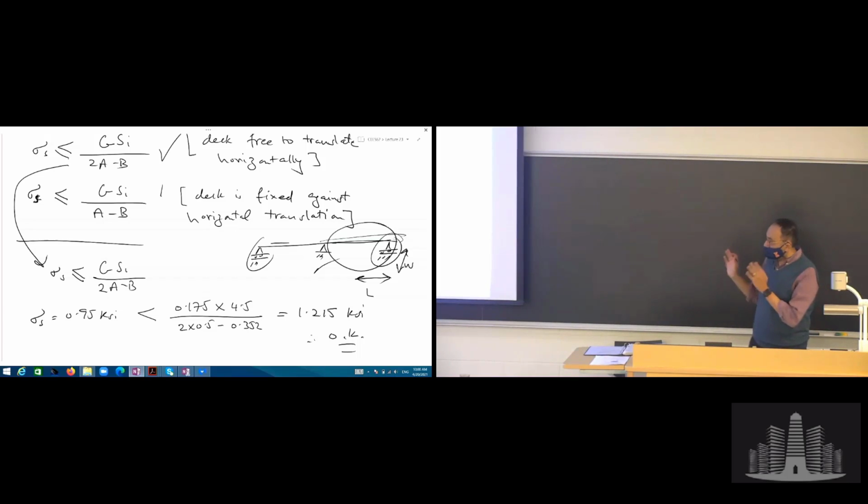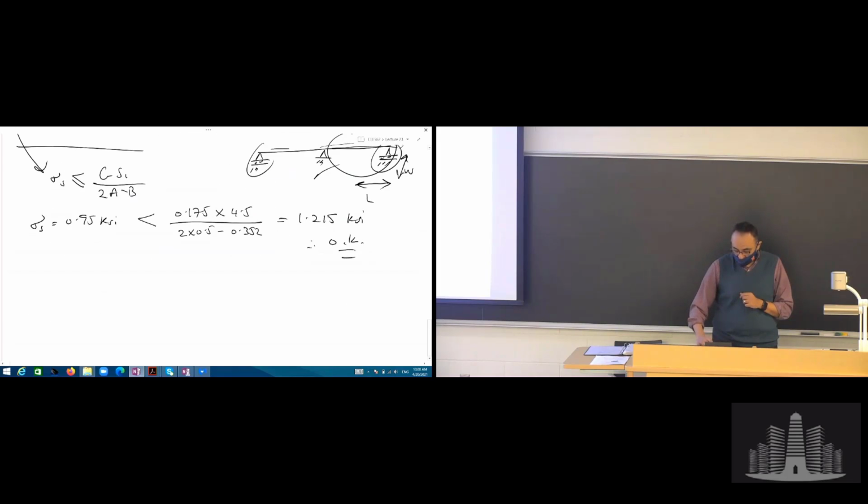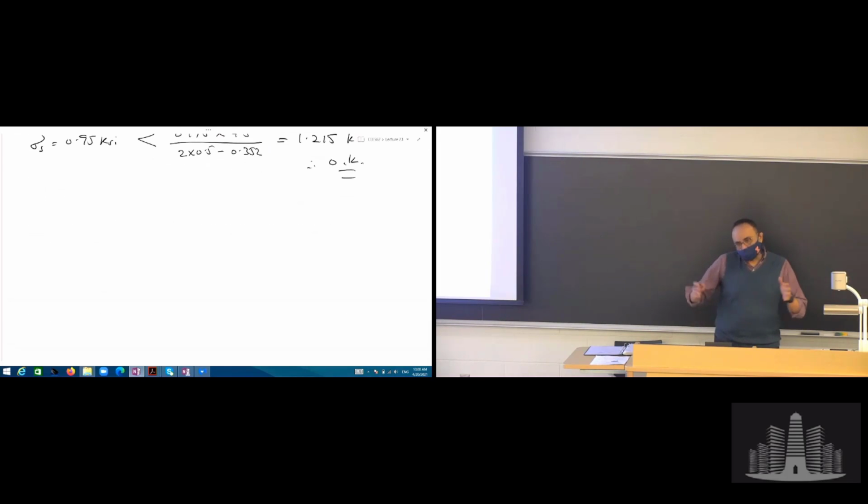Okay, so far we have been talking a lot about the elastomer, the rubber part of the bearing. There is a steel part, remember, that's reinforcement we are providing there that would eliminate, or reduce, I should say, the bulging of that rubber and provide stiffness. So the last step in the design is to come up with the reinforcement. So that's step number 8, reinforcement.